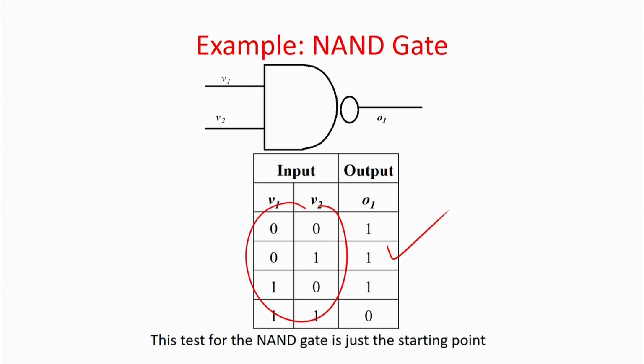For example, if I had manufactured say 10,000 NAND gates, maybe out of that 100 will have some failures, because the technology to fabricate the NAND gate is not matured, but still I am using the technology, because now my NAND gate size will be very small in the nanometer technology, and I can cram millions of transistors and gates in one chip, so that I can give a good product to the customer. That basically is the idea.